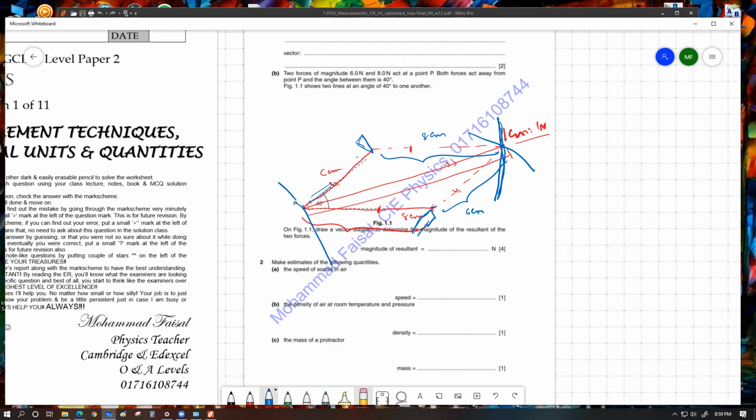They have only given you two lines representing the 40 degree angle, but the given lengths along the angle are not of any use to you. These are the alignments you can use to draw your diagram. Ultimately, we have to extend these and draw them longer. The lengths of these two given dotted lines don't actually mean anything. This angle is just provided to you so that you don't have to draw the angle anymore using a protractor. That's the only benefit.